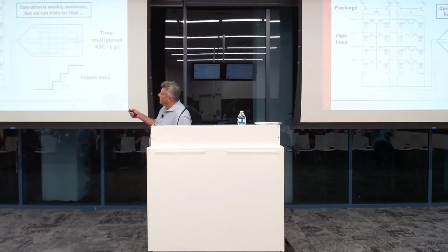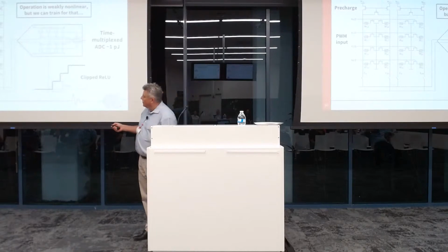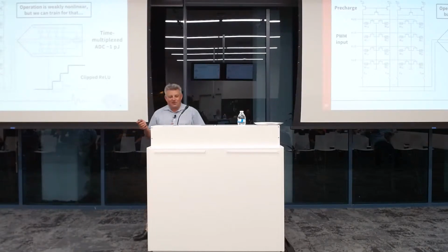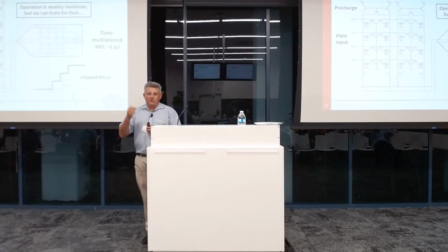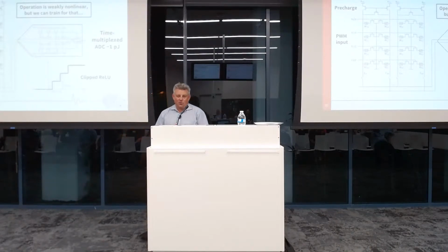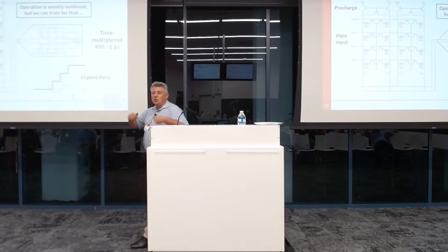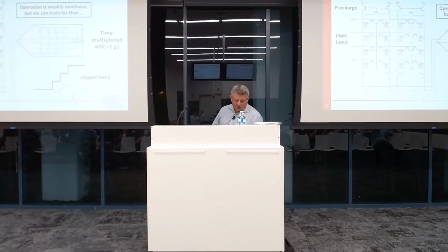And we're doing this in the voltage mode. This is sort of detailed for the analog guys. You could think about throwing transimpedance amplifiers here to sum the currents and so on. You can forget that. Forget 1,000 tops per watt if you want to build linear amplifiers that are low noise and stuff like this. All of this stuff has to be very lean and dynamic and no current unless there's actually an operation to be done, and so on. So we're studying these things, and I don't want to talk too much about it. Turns out the ADC can take about a picojoule. That picojoule has to be amortized over many, many rows, otherwise it will kill you.